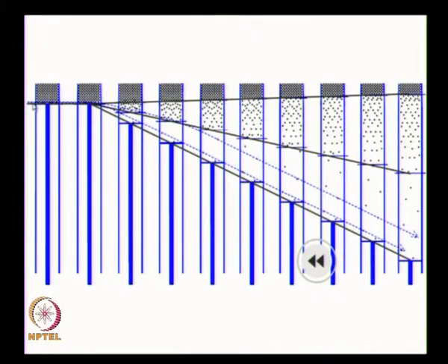What I wanted to show now is this streamline drawn here. We said that it is tracking of a particular particle, especially this one and this one, as a function of time, and that becomes your streamline if you look at it in 2D flows. Now what I want you to see is they are starting very close to each other, that is the gap between them is very small. If you go back to understanding fluid mechanics, the stream tubes can be considered as the streamlines in this case in 2D flow, right. The streamlines will form the stream tube in 2D flow.